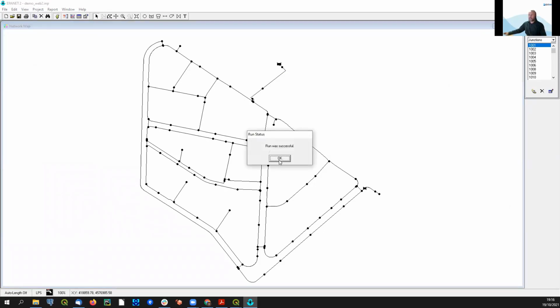In this case, the run was successful, including an on-the-fly transformation, because this object in the first exportation was a tank, as there were sources to provide water. But in this case, as this is the header object, it's not a tank, it's a reservoir. This is the kind of on-the-fly transformation that Giswater does in order to make work as easy as possible for hydraulic modelers.